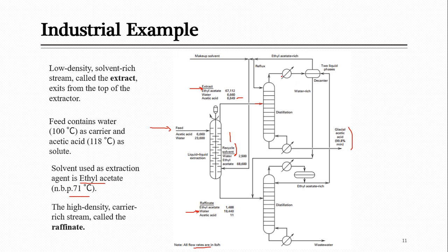So now this was a mixture coming from the distillation column, a mixture of ethyl acetate and water which came from here. Acetic acid you have already removed, these two come here, they get condensed, and they go to the decanter. In this decanter you get them separated into two phases. What are those phases? One will be water and the other will be ethyl acetate. Now which one is the lighter? Definitely ethyl acetate. So ethyl acetate will stay at the top and water will be at the bottom.